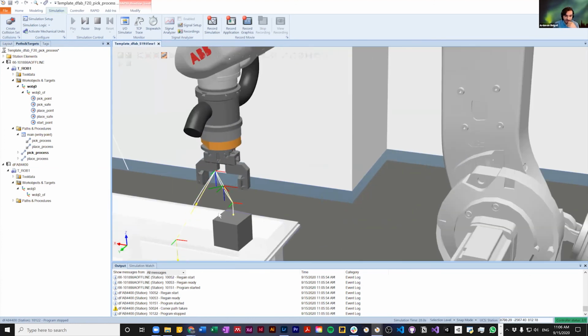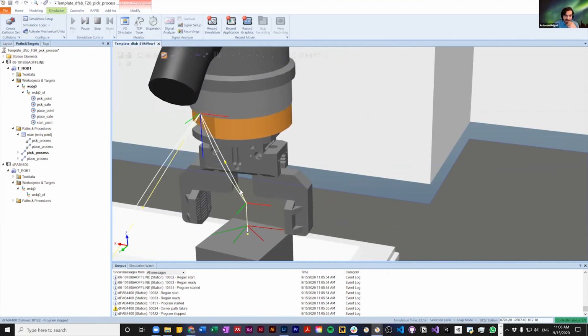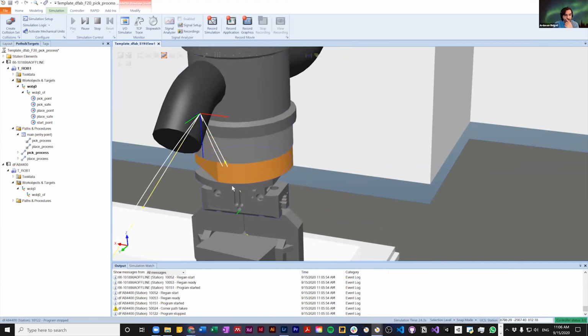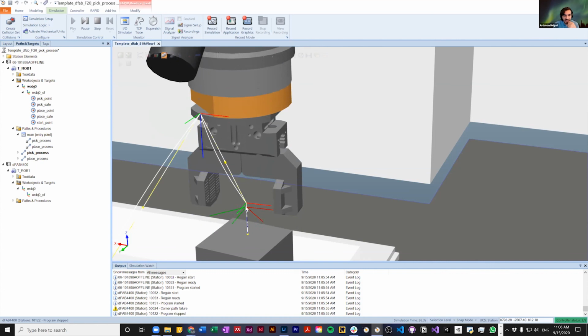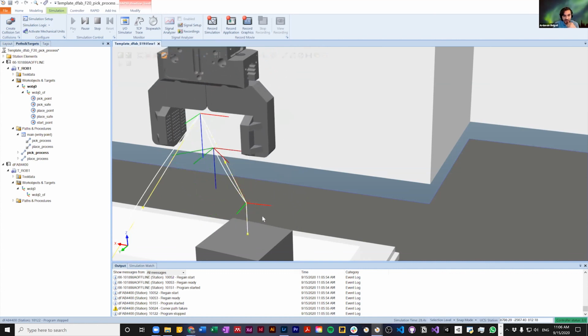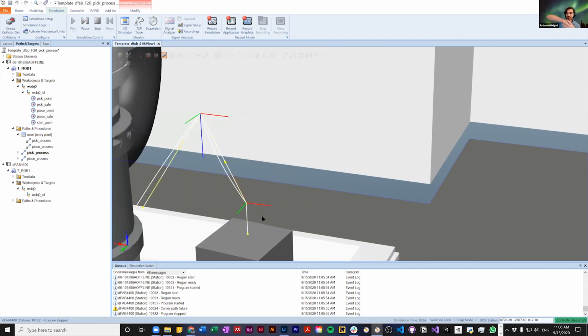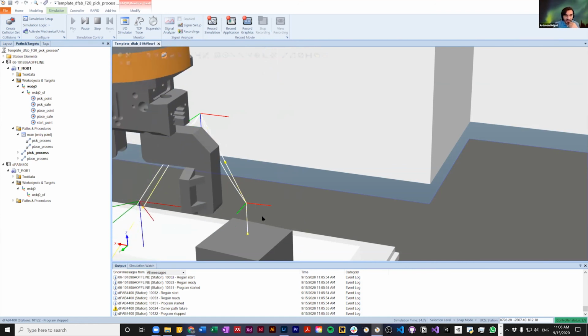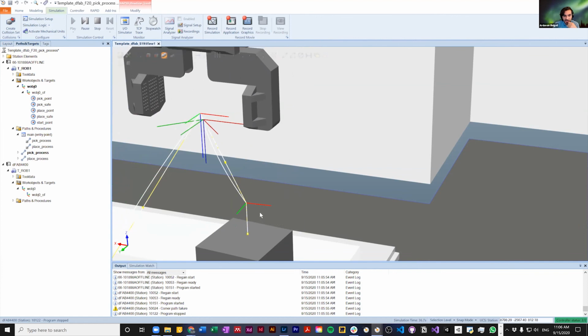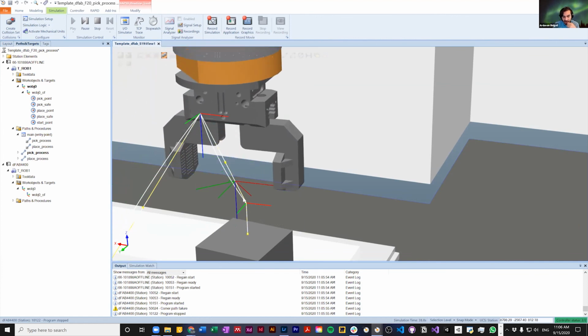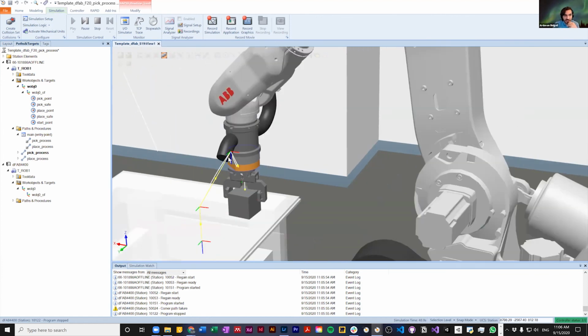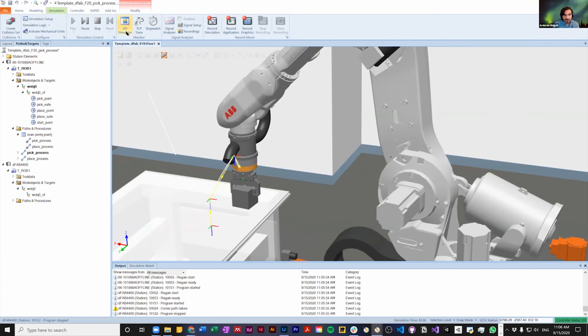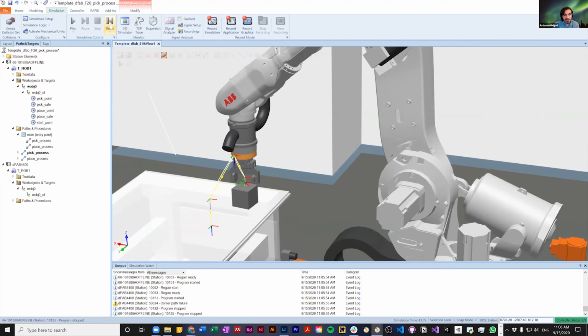And now if you look carefully, you will see how that MoveL and MoveJ are different. So this path that's moving right now is a MoveJ. So the robot just moves the easiest way it can. But at the beginning, it uses MoveL, which is completely linear. This is MoveL. And you can actually continue this simulation for thousands of times. But you can at the very same time